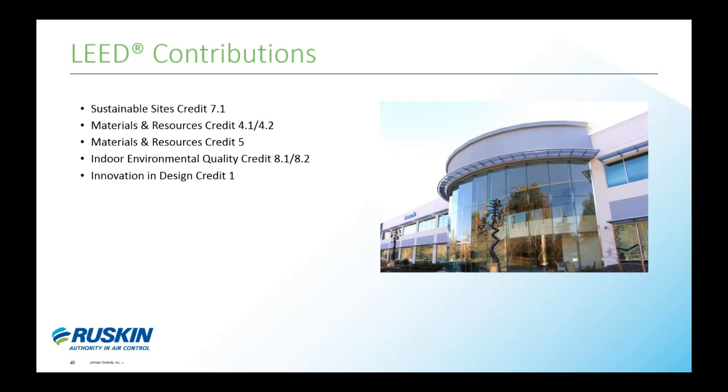The intention here is to reduce the heat islands. It's to minimize the impact on the microclimate and habitats. What you can do to implement it is provide shade to 50% of the site area within 5 years of occupancy. Or this credit is achieved by increasing levels of energy performance above the prerequisite baseline and reducing the environmental and economic impacts associated with building energy usage. The demonstration of gains would be to run models with and without sunshades to show your improvement.